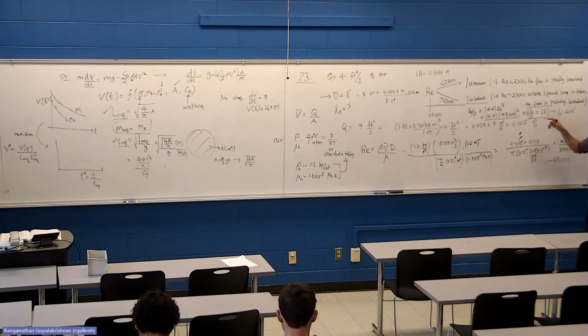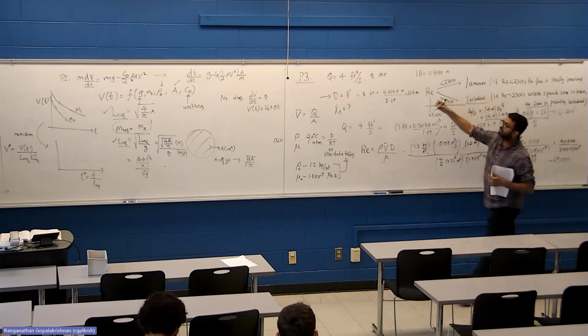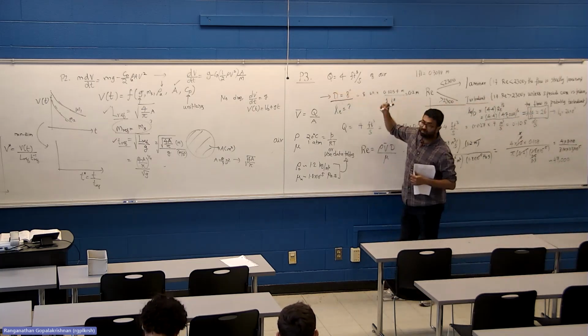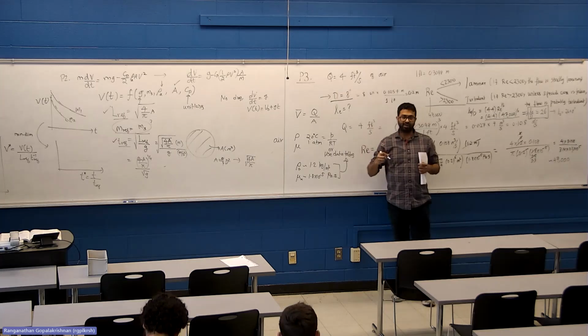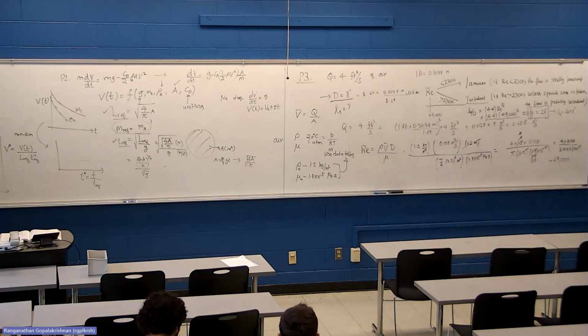Very common practice in fluid mechanics to talk in terms of diameters. How much is the entrance length? Oh, it's about 26 diameters. You always define your local scale based on the problem involved. It could be 8 inches or 8 feet, but the fact is, it is 26 diameters.